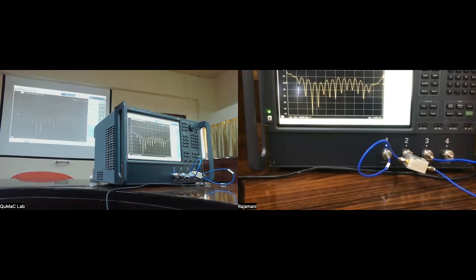However, the catch here is, or there is one special mode, if both of these signals are at the same frequency. The reason I'm talking about same frequency is that earlier I said if these 2 are independent signals, what I mean is that there's absolutely no phase relationship between the 2. So when the frequencies are different, you cannot define a fixed phase relationship between them.